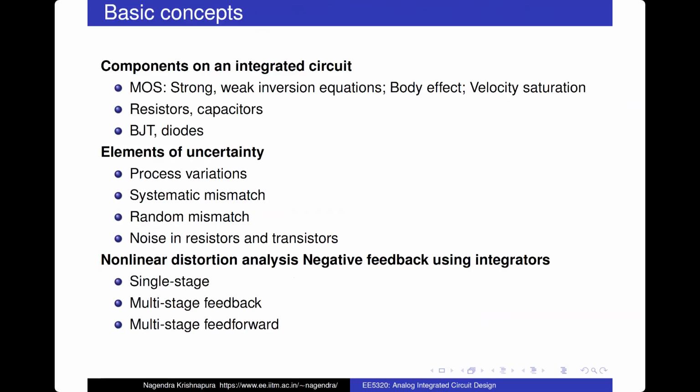The kind of op amp that you would have seen in analog circuits is what is known as a single-ended op amp. That is, you have a differential input and just one output terminal, and the output is defined with respect to ground. Whereas the preferred mode of implementation on an IC is fully differential. The output will also have two terminals, and the difference voltage between those two is the relevant signal. Okay. You need some special circuits to make those things work. We'll look at that.